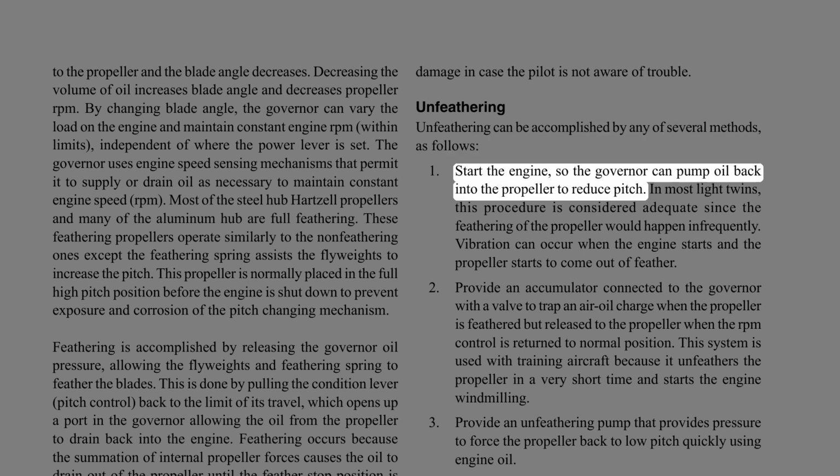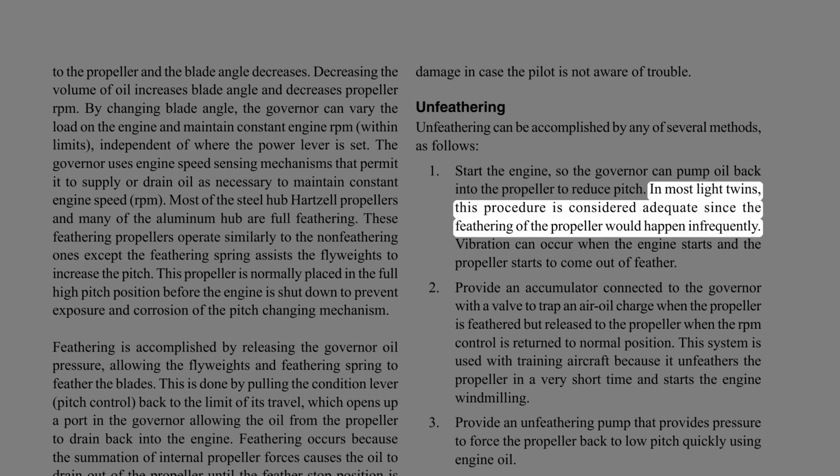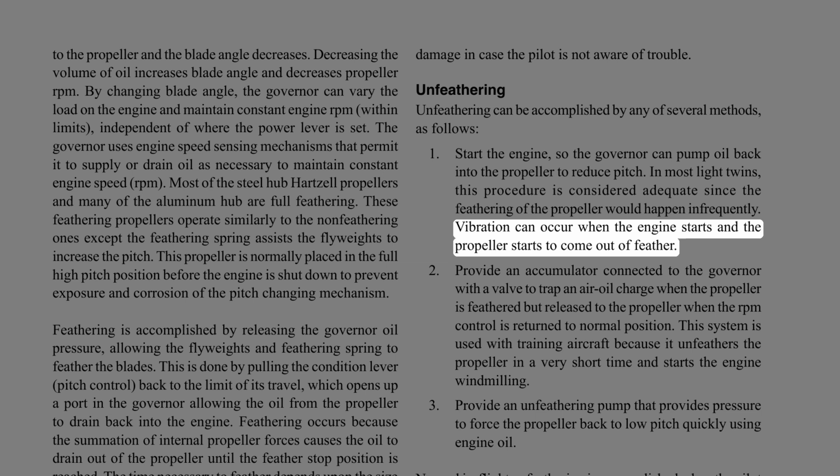Start the engine, so the governor can pump oil back into the propeller to reduce pitch. In most light twins, this procedure is considered adequate since the feathering of the propeller would happen infrequently. Vibration can occur when the engine starts and the propeller starts to come out of feather.